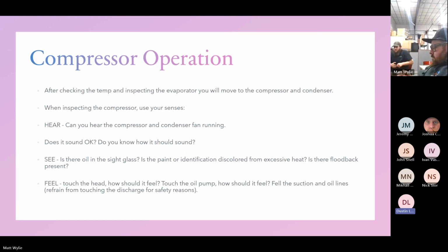But there's really no way to know, when you land those 3 legs of power, what the rotation is going to be. So always verify the rotation of your compressors. That's why when you do a startup on an AC unit, you always check the blower rotation. You turn it on, you turn it off, you make sure the blower is spinning the same direction as the arrow. You check your refrigerant pressures to make sure your suction's dropping and your discharge is rising. You check your amp draws.